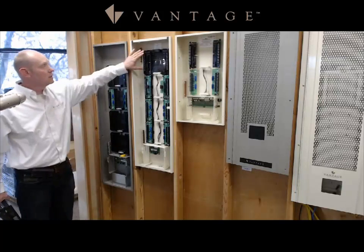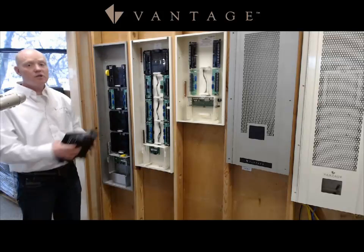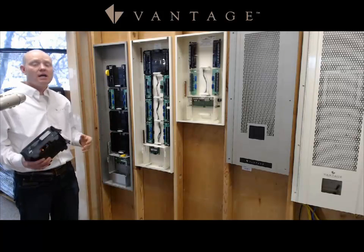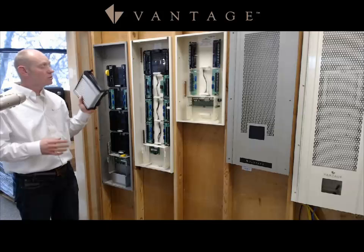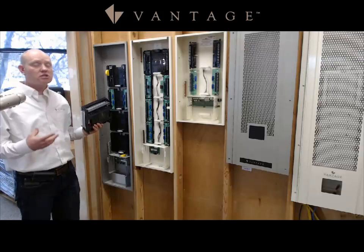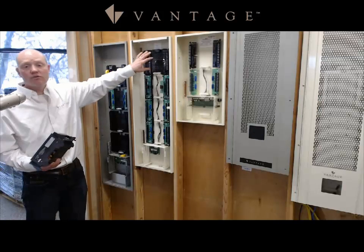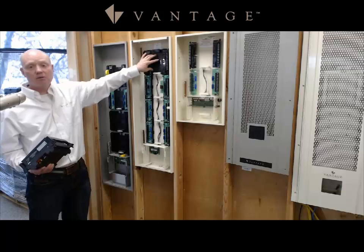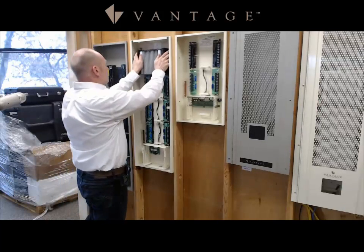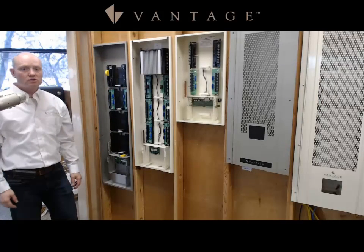Another thing to point out: in the old dimmer module enclosures, you've got the ability to put in the new standard dimmer module as an 8 load module. So even on an old Q-Link job, if I've got a module that goes out, I can replace it with the new 12 load. It's only 8 loads capable on it, but I don't have to make any changes to the software or anything like that. Same thing with Infusion jobs. I can go in, use the retrofit boards, flip over the black back box and use the wiring harness just the way that it normally was, and I'm good to go. So there you go. There are 2 new enclosure modules.